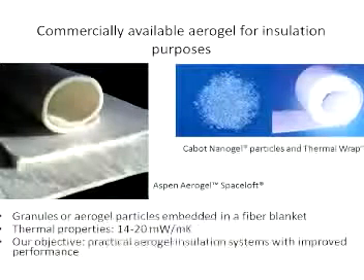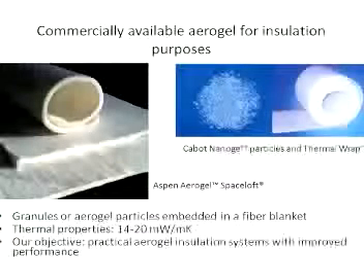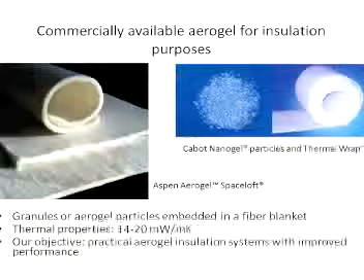And we in the lab are in the middle of a project to improve the performance of this aerogel insulation so that about a half inch of aerogel will be equivalent to about 3 to 4 inches of conventional insulation. The hope is if we can make these into panels, they could be easily retrofitted on the inside of existing buildings as a way to substantially increase the insulation of the walls, but not at the same time cause major renovation problems. So it could almost be used as paneling on the insides of the wall systems.